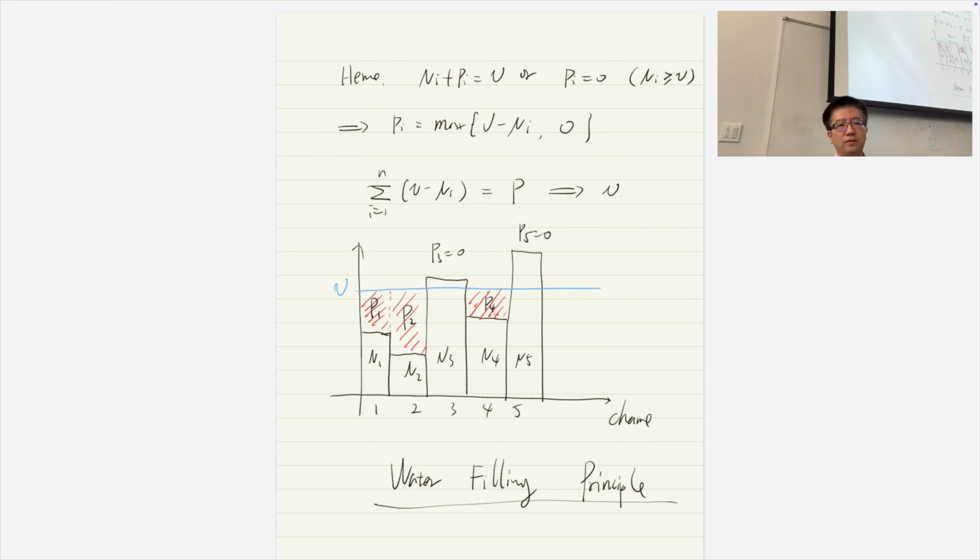So yeah, this is called the water filling algorithm, the water filling principle. It's kind of like pouring water there, okay? And we have a lot of applications in practice. So now you may be wondering, is this a realistic model? Is the parallel Gaussian channel a realistic model? There are a few things, because the noise has to be independent of each other and so on. But actually it is very realistic. So we have applications today everywhere.